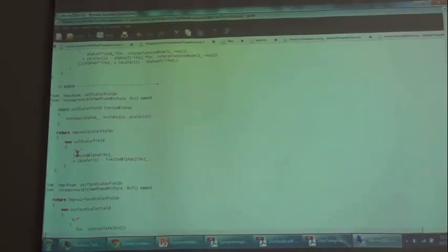DC is basically a mixture diffusivity. The way it's defined is the product of alpha1 times DC1 plus alpha2 times DC2. That definition goes in here, and since you will be calculating a divergence, you will require the face values of each of these DCs that you are creating. So you basically create a surface scalar field here. These are the only modifications that need to be done to your new incompressible two-phase folder.